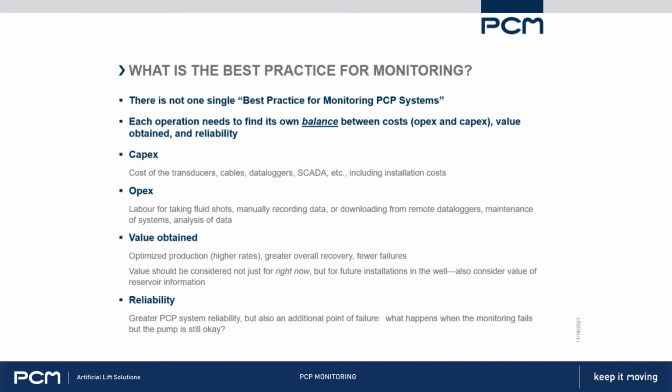So what is the best practice for monitoring? I don't have a single best practice I can give you, because every operation has to find its own balance between the costs and the value obtained, and consider the reliability of the systems as well. So there's cost involved with all instrumentation, whether that's the CapEx of buying the transducers, the cables, the SCADA systems, whatever you're using. And then there's OpEx for labor in terms of going out and taking fluid shots, recording the data, downloading from the data loggers, and whatever maintenance.